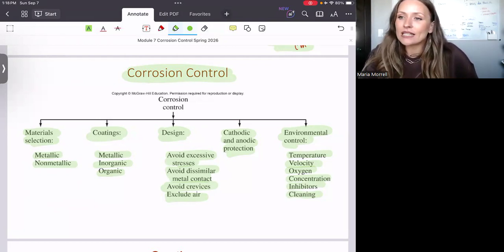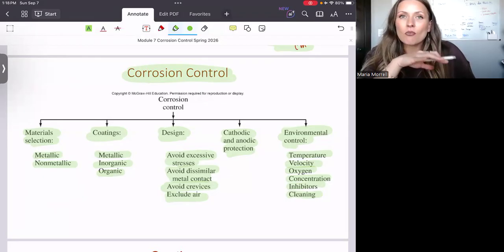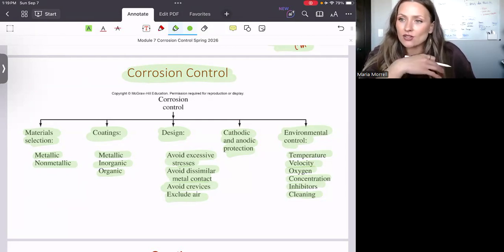And why cleaning, right? Because it comes back to the formation of crevices. Any metal that is underneath a certain debris will corrode. So my genuine advice, if you have a vehicle, and especially if you live in an environment where you deal with dust, dirt, and snow, you need to always make sure that your car is crispy clean, because yes, it will last you for many, many more years than a material that is standing in the dust, even a fine layer, right?